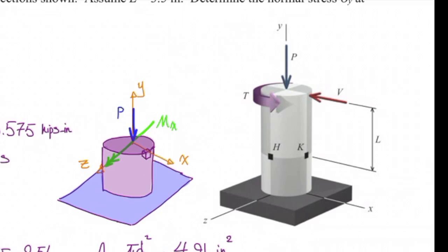What is the axis of interest for that shear force? Z. If I want to determine Q for point K about the Z-axis, how much would be the area for the cut section? 0. So that gives me Q equal to 0. So the shear stress caused by that shear force is 0 at that point. Is there any shear stress caused by that torque? Yes. So that would be simply Tc over J. That's it.